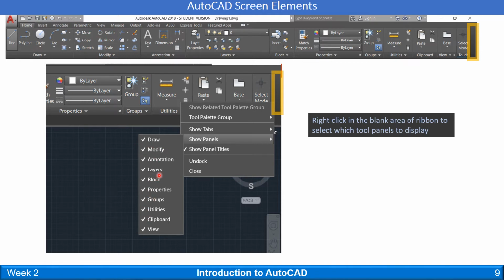If I don't want something in here, maybe I don't know what utilities is and I don't use it, so I'm going to uncheck it, and then it's not going to be in my ribbon anymore. It's not going to be cluttering up. And you probably won't use every single little thing in here. They say most people use just about 5 to 10% of what's in AutoCAD, and it depends on what applications you have, if you're a civil engineer, if you're a mechanical engineer. So you kind of find the tools that you most commonly use, and then everything else you can uncheck and ignore until you need it.